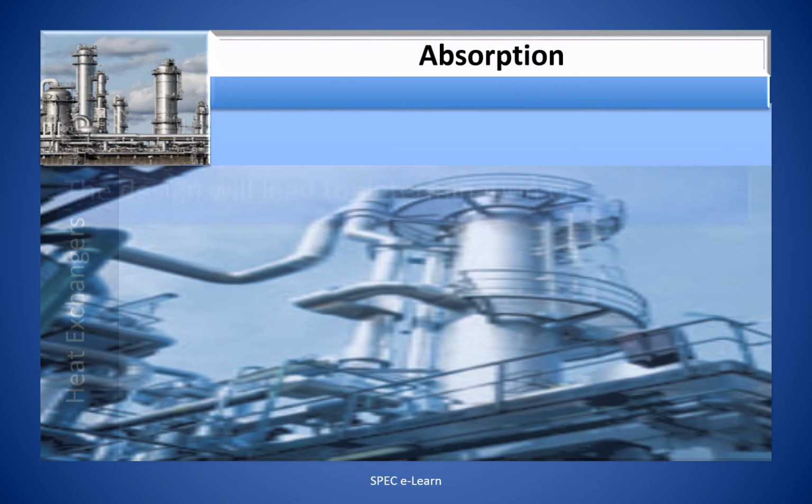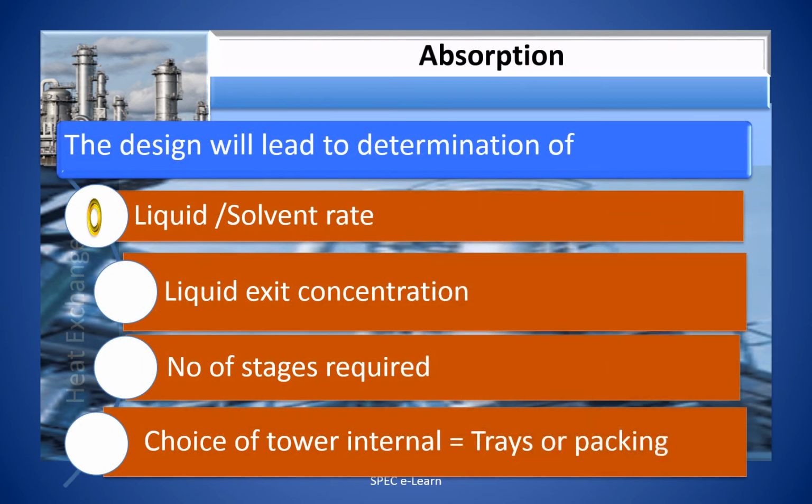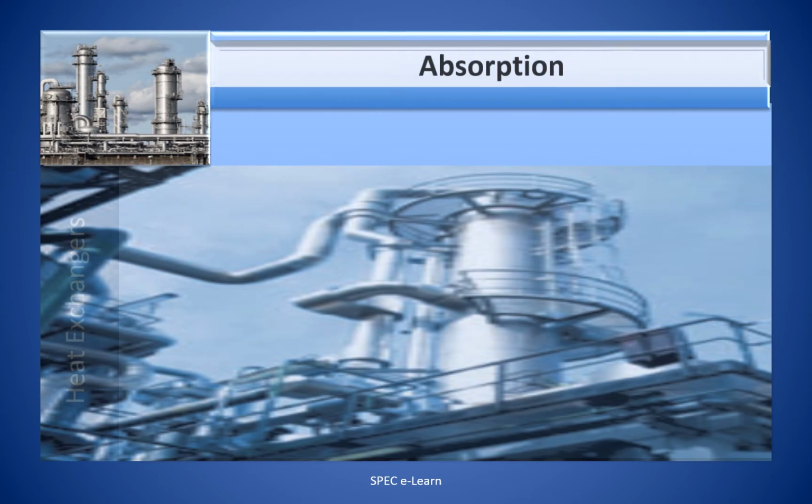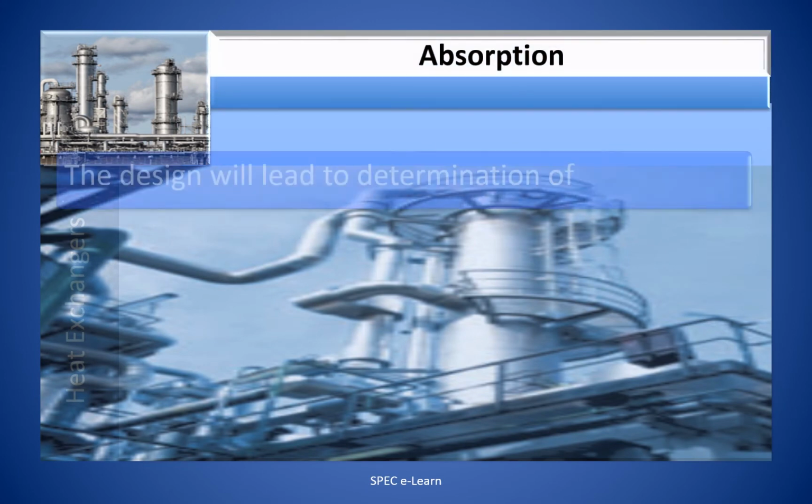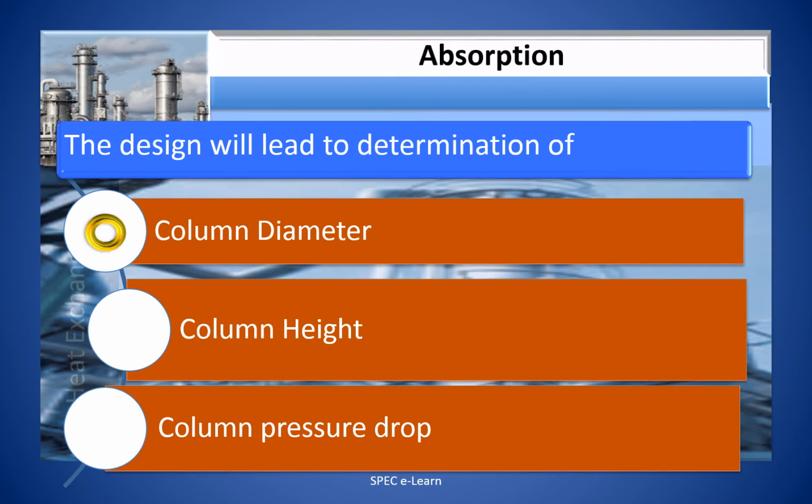In summary, the design will lead to the determination of a liquid or solvent rate, a liquid exit concentration, number of stages required to achieve the degree of separation specified, choice of tower internal, whether it is tray or packing, the column diameter, column height, and column pressure drop.